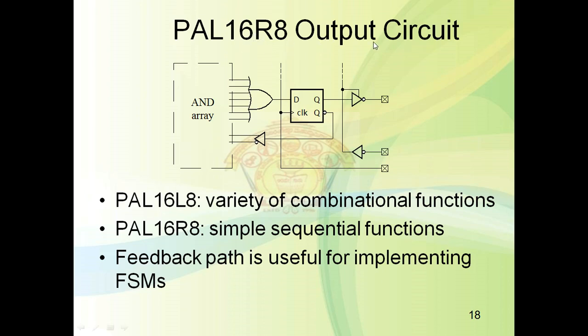16R8 is used for sequential functioning. 16L8 is used to implement combinational functions. 16L8 is used for combinational circuits. And 16R8 is used to implement sequential functions. Sequential circuits can be implemented by using 16R8.